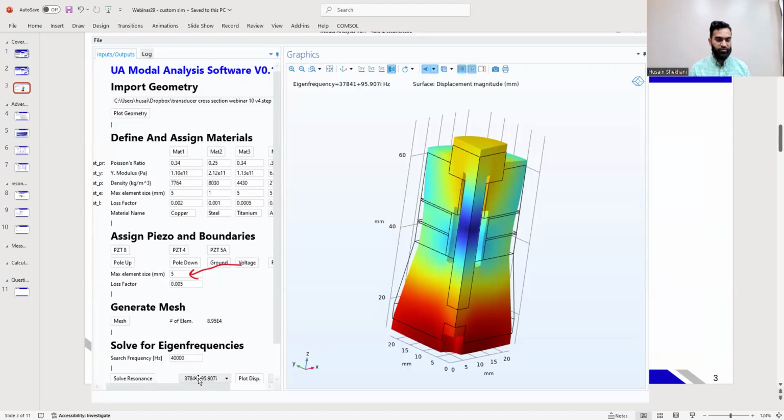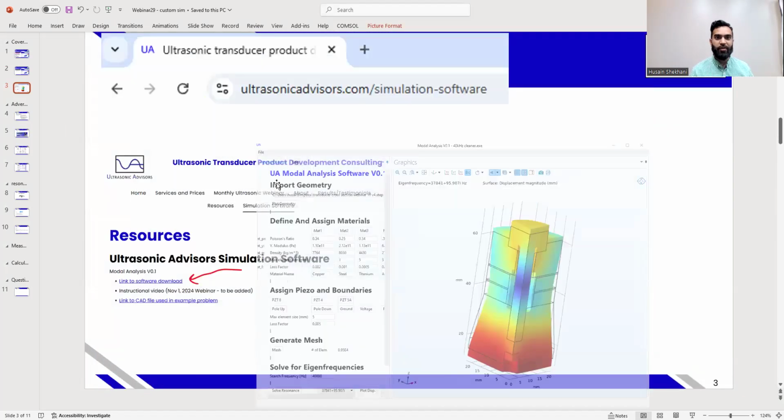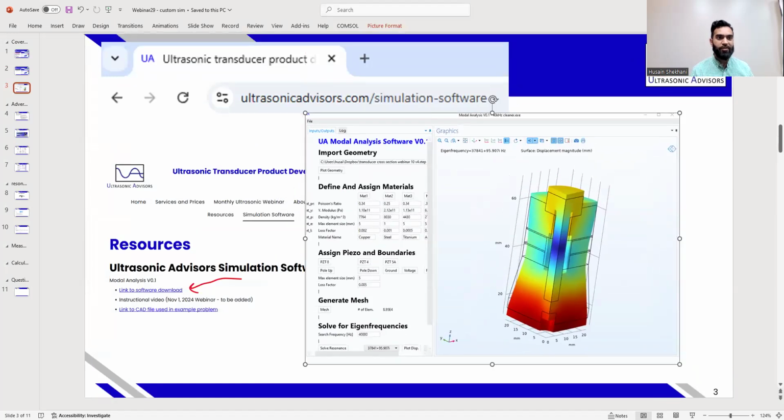You're going to find which one looks the best for your particular application, and you're going to plot the displacement, and you can iterate on this process in order to understand how to design your tools, or change the horn, or what frequency you're driving at, or what's exactly happening at an unwanted frequency. I'll explain a little more about how I made it and how accessible it is, actually.